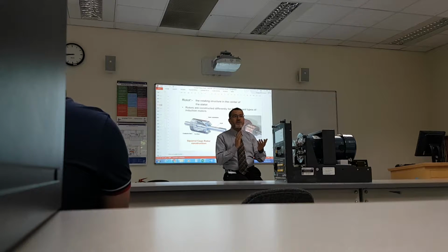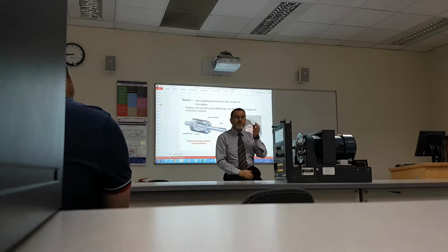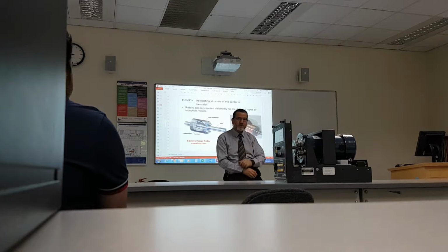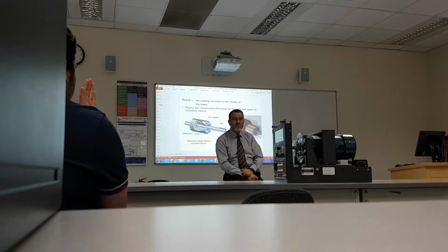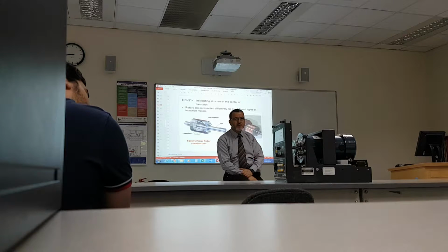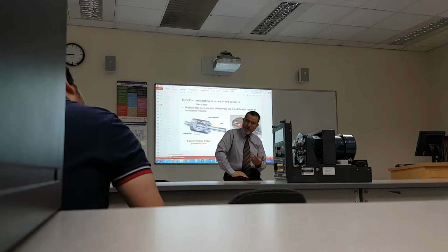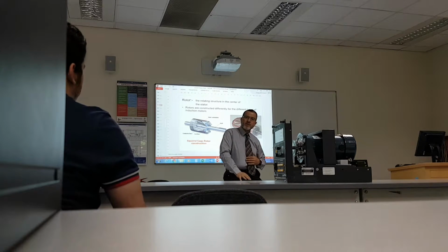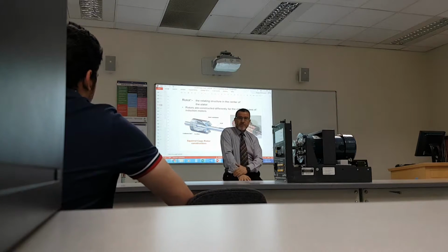So that's why in induction motors, we're not concerned about accuracy of speed. Any application that requires accurate speed control, you need a synchronous motor. So basically it's going to slow down until it reaches its rating. If you went above the rating, it's going to stop. Not for induction. Induction never stops, because of slip. Of course, it can lock the rotor if you go way beyond, or it can burn.